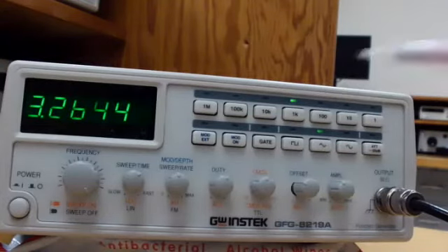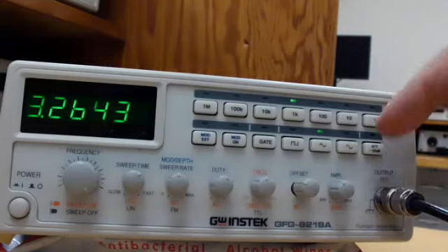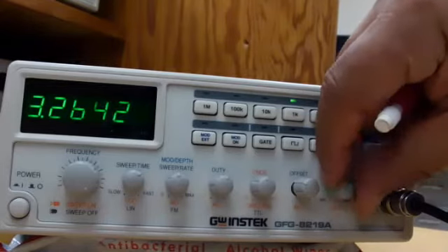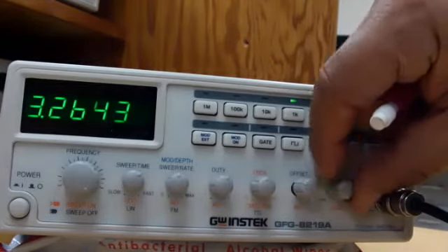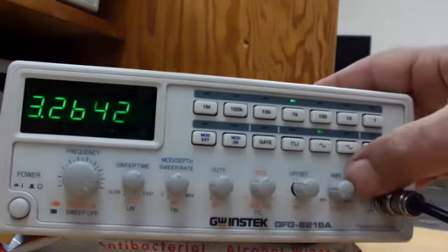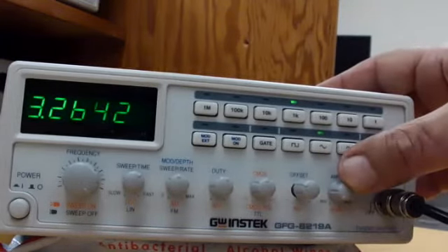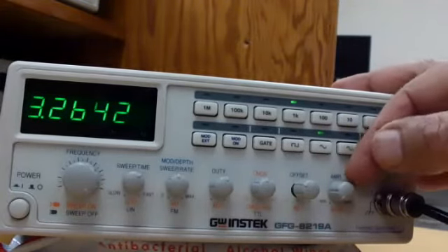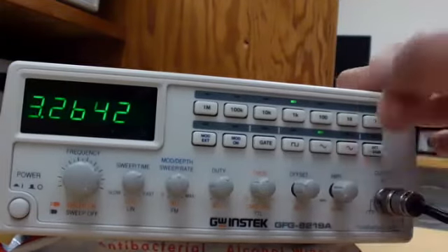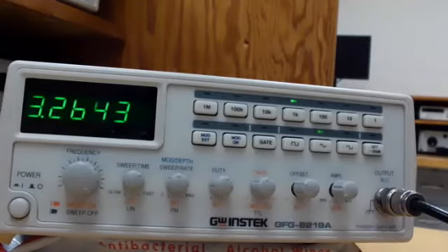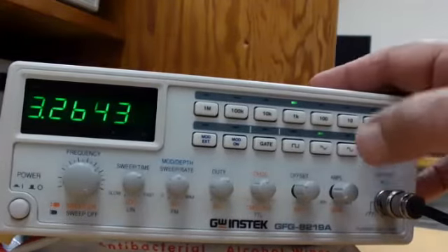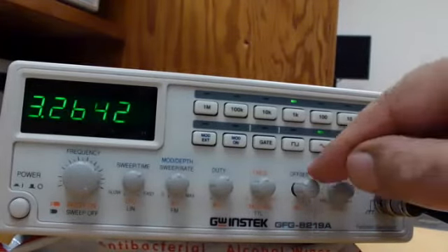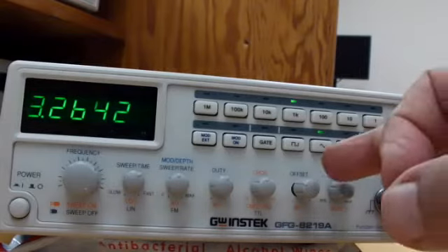What other thing? Well, this button is the amplitude. If you turn it clockwise, you're increasing the amplitude. If you turn the knob anti-clockwise, you're decreasing it. But observe, it's in the normal position, pushed in, and in this position you get normal values. In some applications with digital, you have to pull it out. It will give you a small range. But in our experiments we are not using the small values, so you have to keep it pushed in. The second one here to the right is the offset.